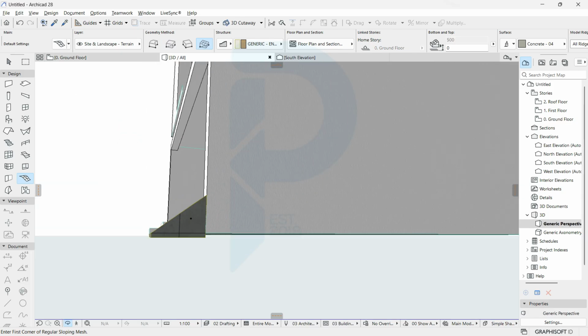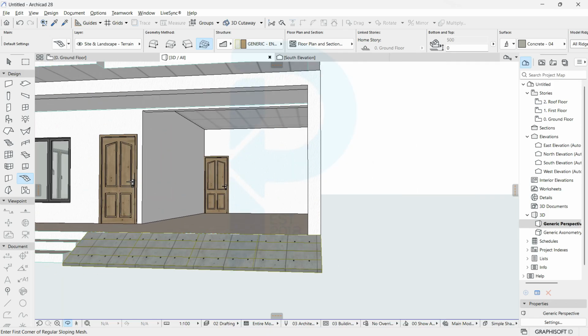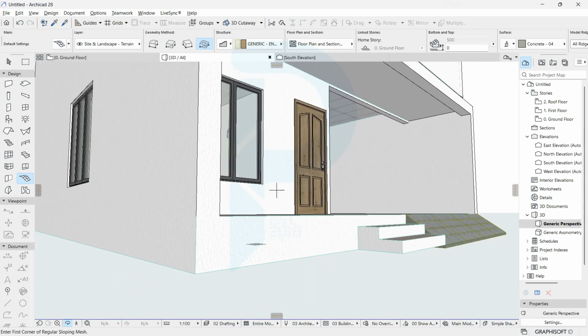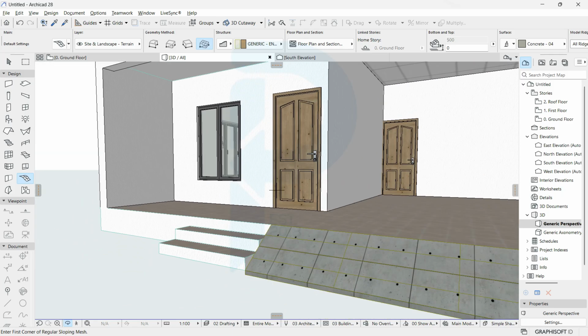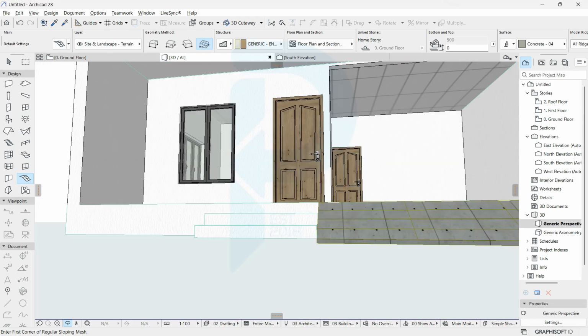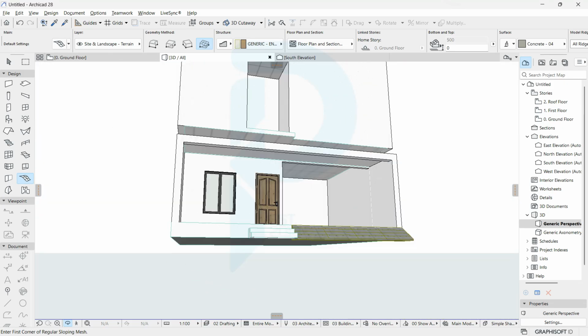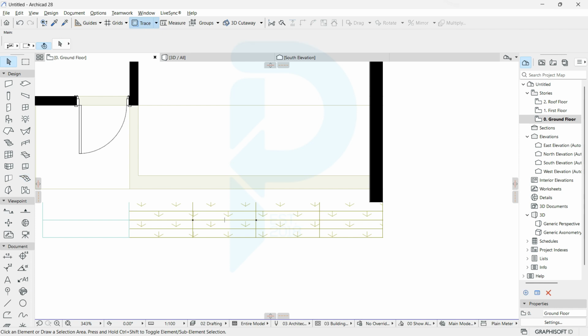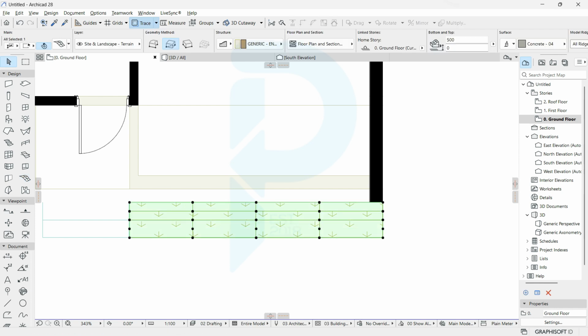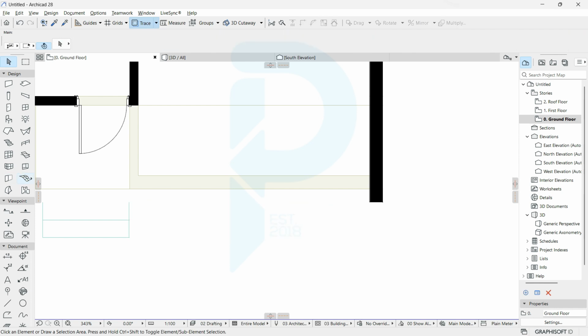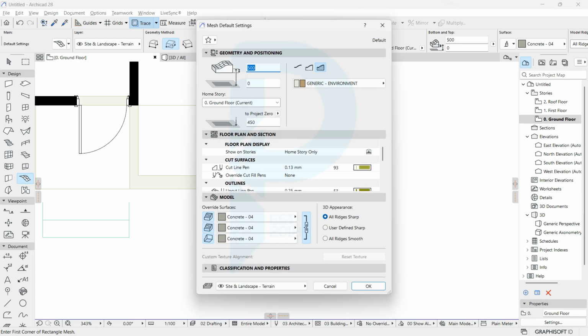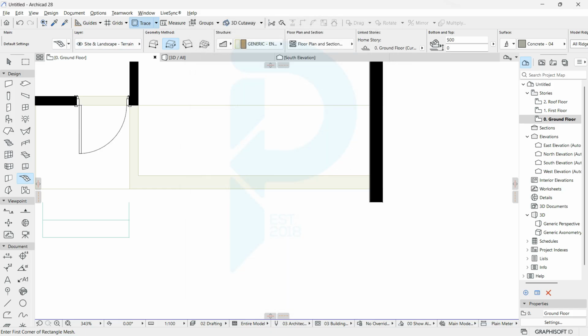I think it's a bit too sharp. Yeah, that's too sharp. If a car is driving up there, it's probably going to cause a problem. I think I should do something. I can adjust that. No, let me do that now, because it might be a concern later on. So it's too sharp, so what we do is just do another one, but make it a slope of 300 instead of a slope of 150. So click OK, and then I'm going to do this.